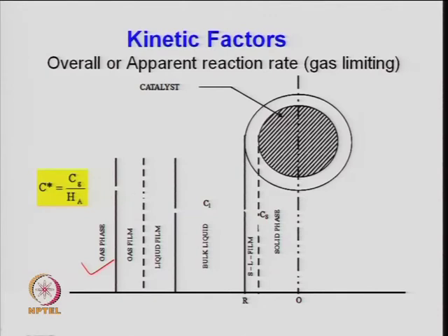So, there will be a concentration difference across it, and then there is the transport governed by Henry's law, given by an equilibrium relationship, P_A equals H_A times C_Ai, or this is the C_S star, the equilibrium composition, which is the gas phase composition divided by the Henry's law constant. So, either way one can write it, depending upon the unit of the Henry's law constant.